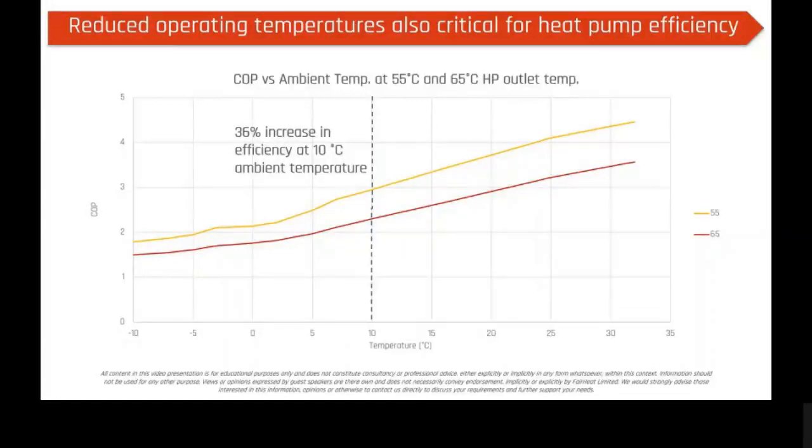And this all comes back to the decisions I mentioned at the start: what do my dwellings receive, and how many substations do I put in, because that's defining what operating temperature my heat pump will have to run at. If I add a heat exchanger, then I'm going to have to raise that by 5 degrees to get that transfer across. If I put in radiators sized for a 70-degree flow temperature, there's no way I can ask the heat pump to operate at 65. So starting at the dwelling and linking it back is how we get the optimization of operating temperatures for heat pumps. You can see the size of the prize available there in terms of the efficiencies of getting those temperatures right.